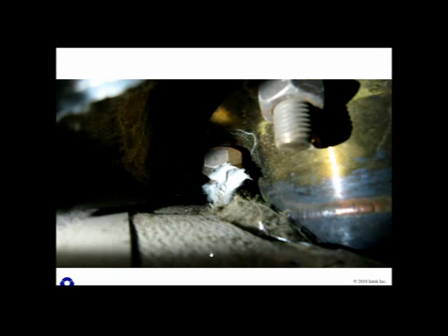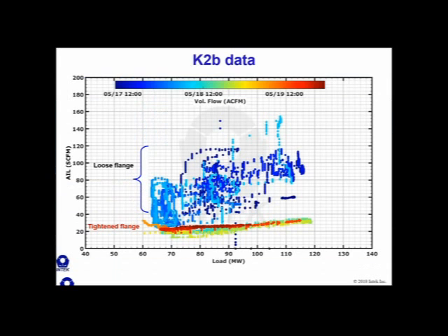There's a large amount of air entering this area, and you can see here that the nuts on these bolts of this flange were not tightened, and so this flange was leaking quite a bit. So after we left, the flange was eventually tightened.